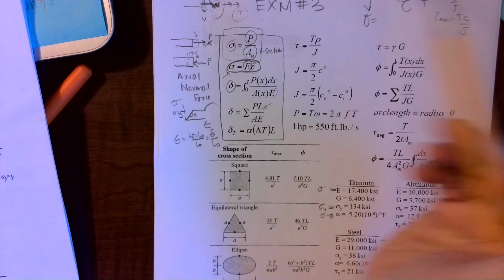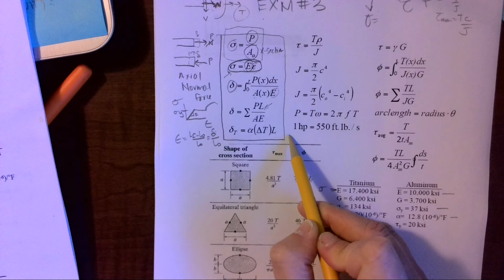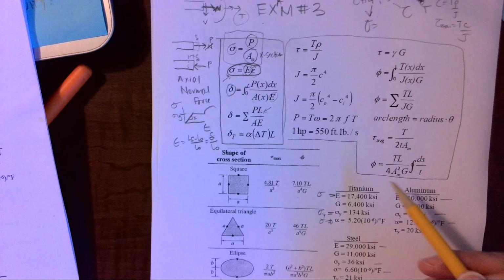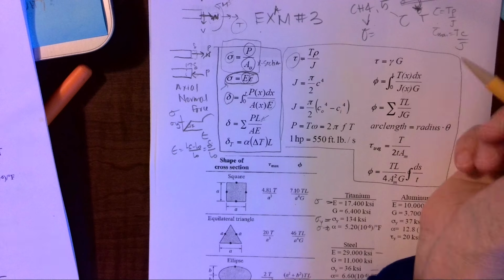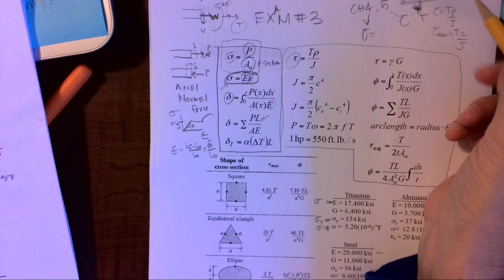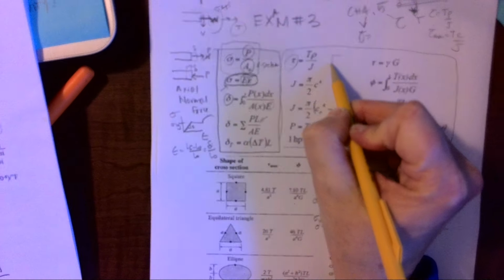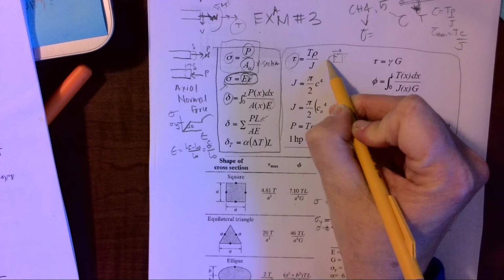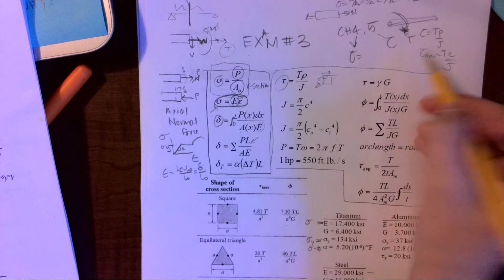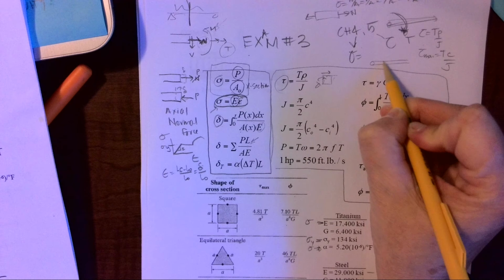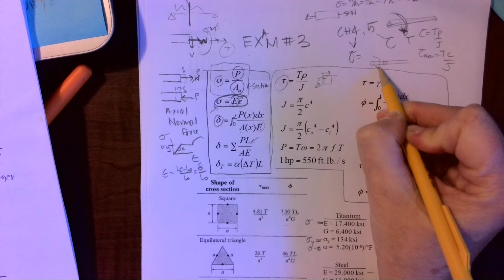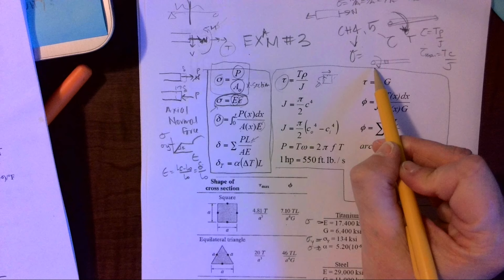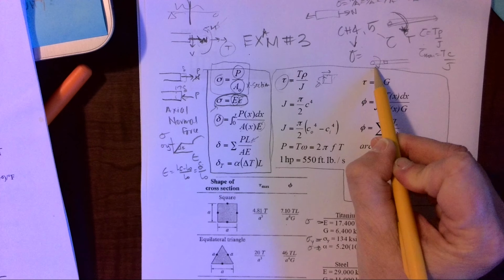Then we have this section. This is shear. Tau is always shear. Shear is that skewing. We originally looked at a block that maybe we applied a load to, and we got this gamma, our shear strain. If I were to look at a shaft that is spinning and I put a square on the outside, as I apply that torque, those outer fibers, you can see that we're going to have a skewing of that rectangular section. We are not changing the length. We are now twisting about itself.